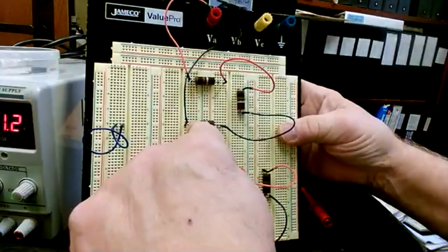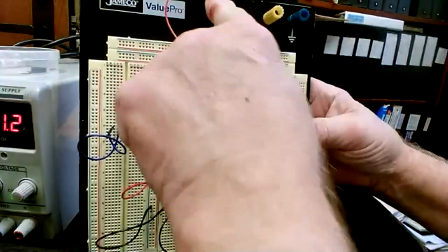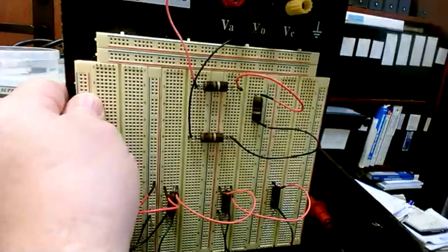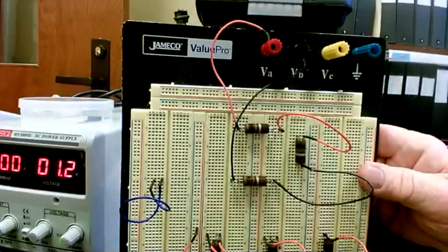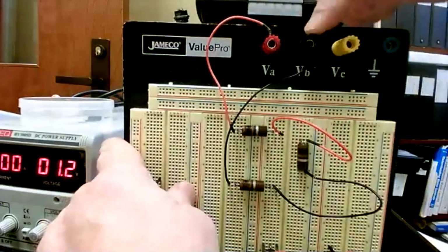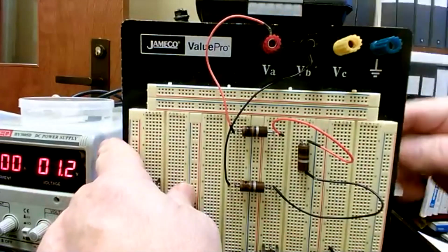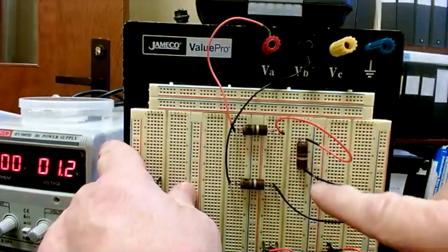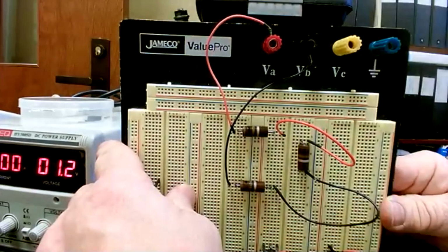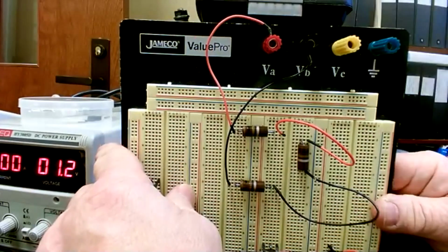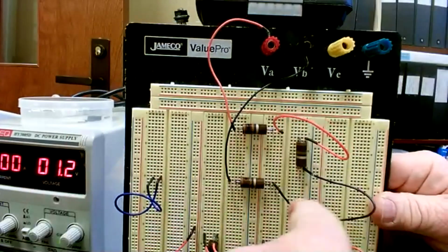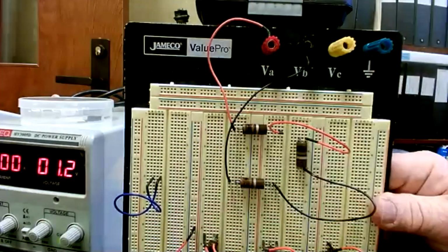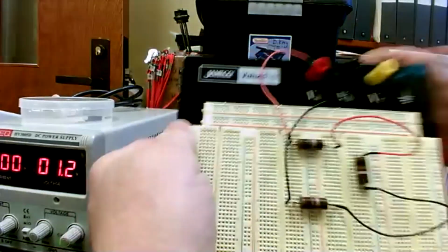I'm going to leave there and go back up to here. I'm going to put a plus. I'm going to put 12 volts on the connector right here. 12 volts plus, and then I put the common right there. And we have a series circuit. Do y'all agree it's series? Yep. You got one path all the way through, and then it goes back to the negative on the power supply.